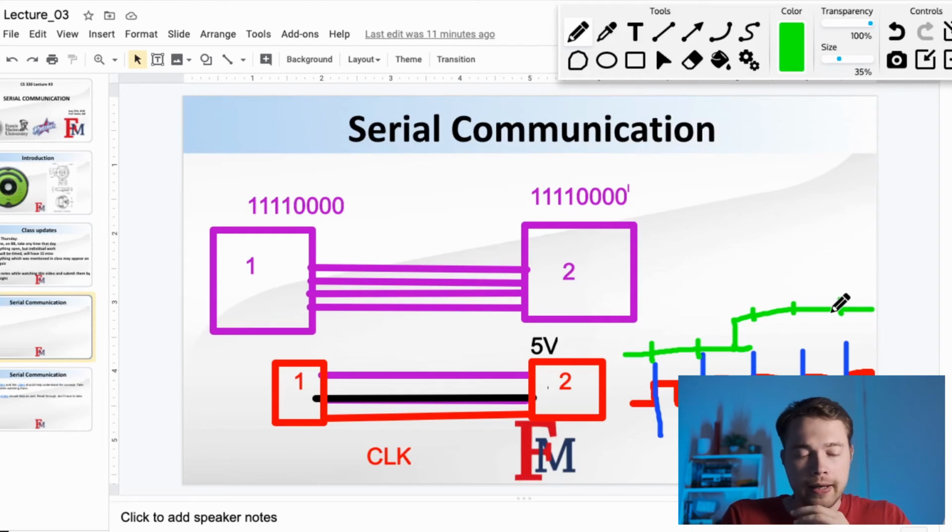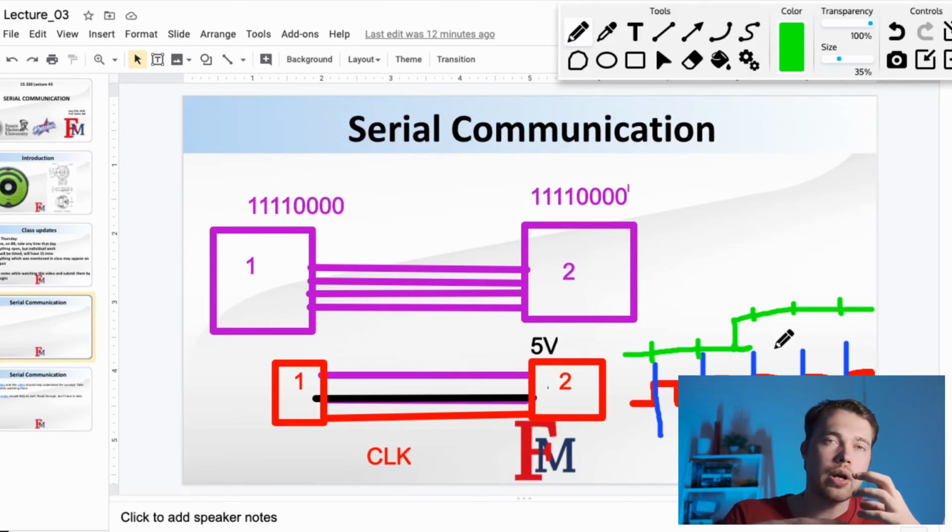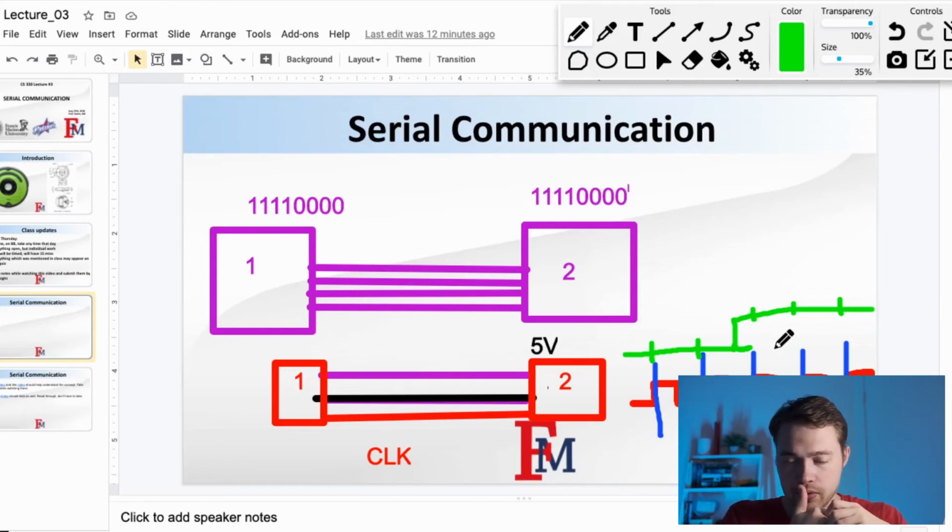That's how it works. This approach, when I'm sending you the signal and the clock, is called synchronous, because we synchronize the clocks. The approach I was talking about before is called asynchronous, where we agree on some kind of timing, for example every half a second. In realistic numbers, it's going to be a couple of microseconds. So every microsecond, I'm going to send you a new bit. That's how it usually works.